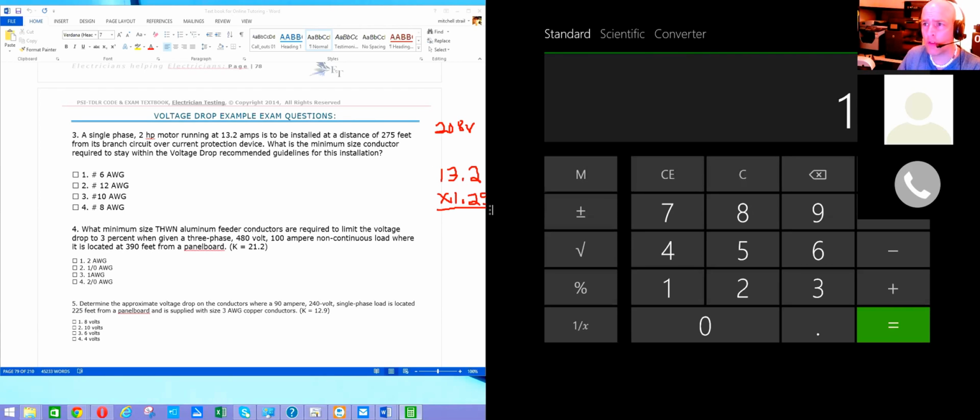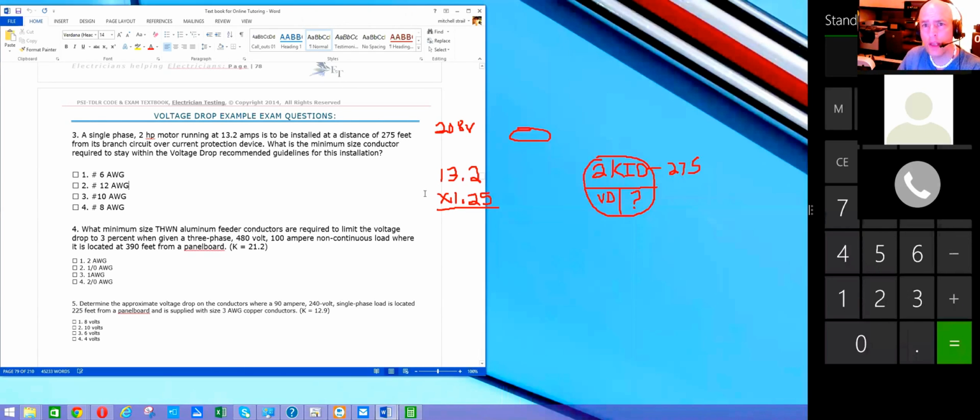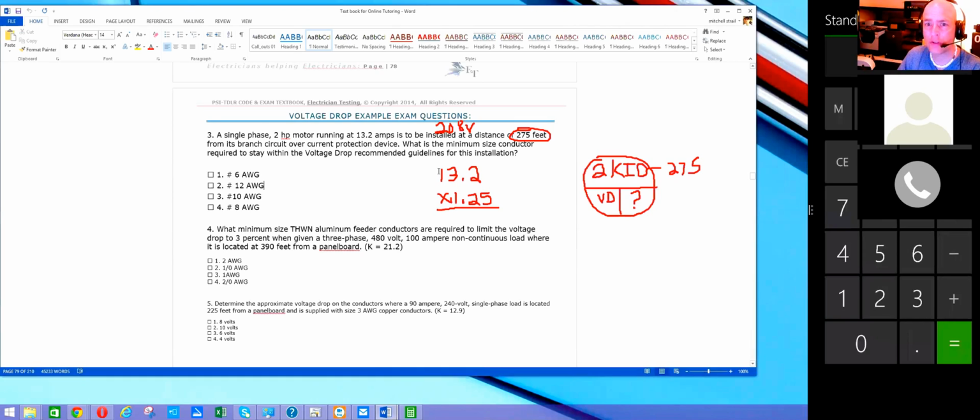So one way or the other, this 16.5 amps is what we're looking at at the end of 3 hours on this problem. Because of that factor, we're going to take that I value and plug it in at 16.5, not at 13.2. You wouldn't have gotten that on your own because I didn't tell you about it, so don't feel bad if you didn't do it. This might be why your answers don't come up exactly right.